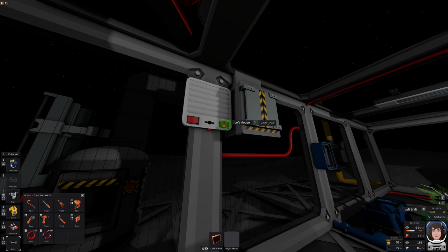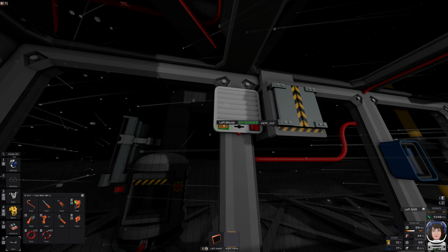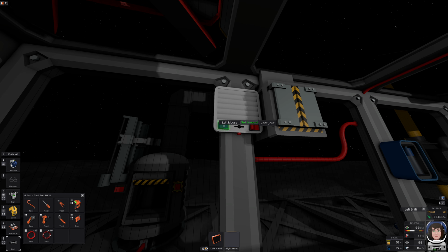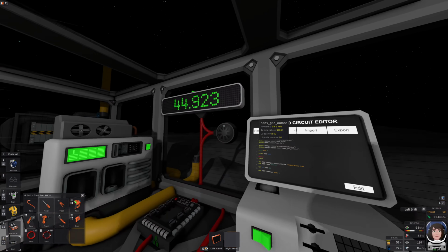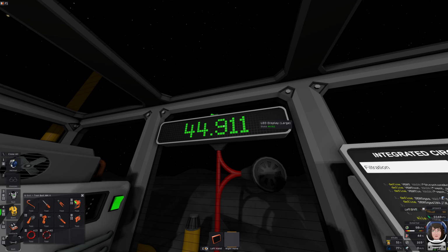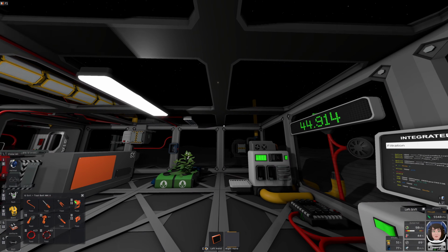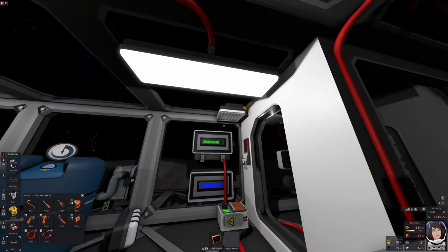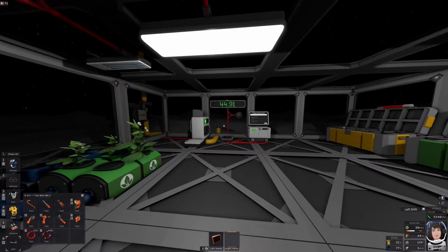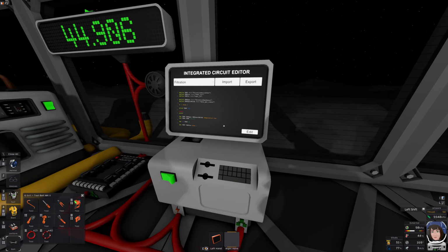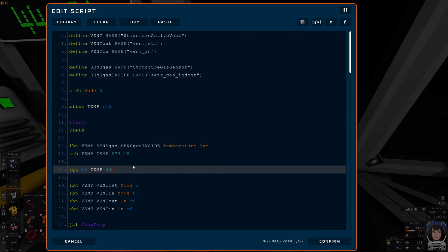It's always good for debugging to try to operate them manually. You can see they are being addressed. They are being overwritten by the logic. So the logic has decided that things shall not happen. Why? Well, the temperature is for whatever reason falling. I don't quite get why. Maybe there's some non-insulated stuff up here, for example, which bleeds thermal energy into the outer atmosphere. That might well just be the case. When the sun is back, I guess we're gonna be glad that we have cooling.